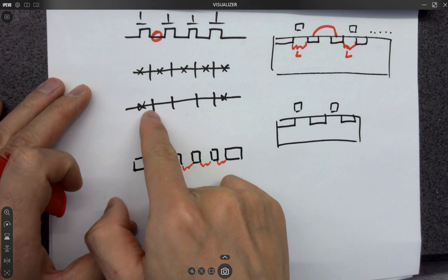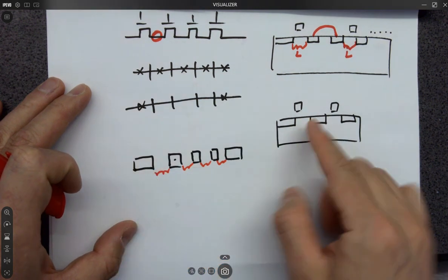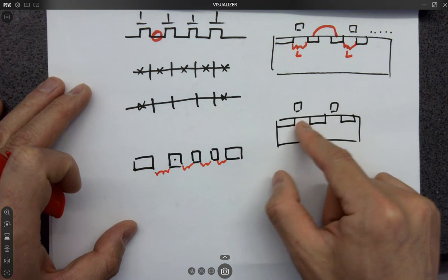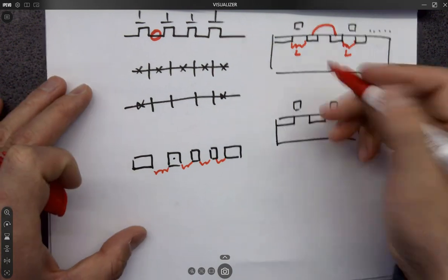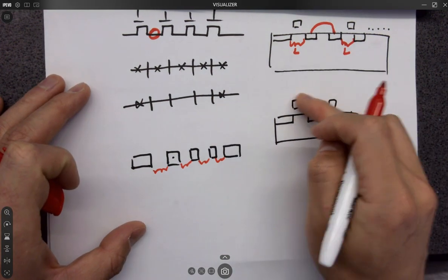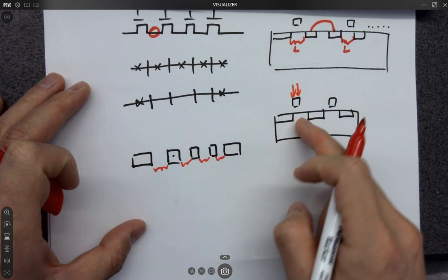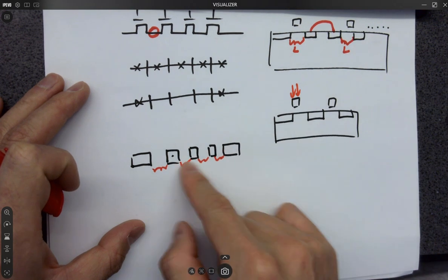But you just have to have the gate in order to open up the wafer's channel area. Because when we do the diffusion, we have the gate on the top. That's why it blocks all the P plus or N plus materials from getting into the wafer, right? That's why it's forming a channel here. Okay.